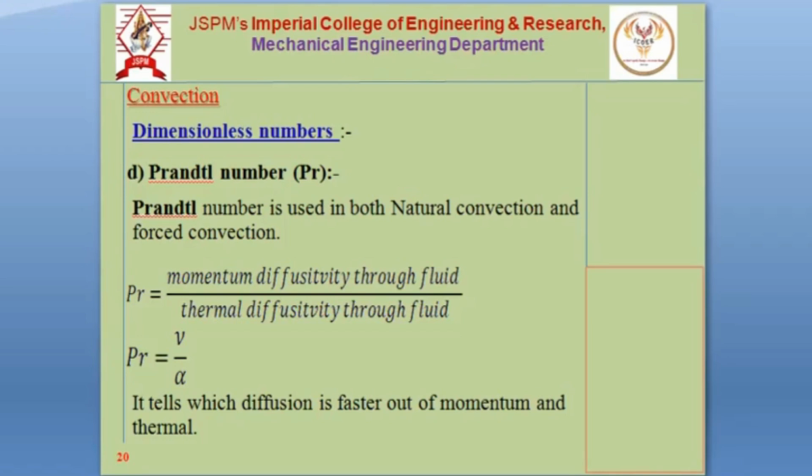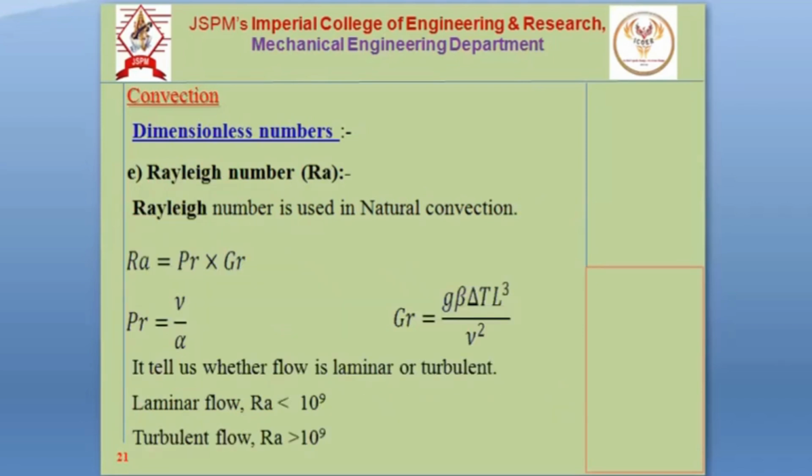Okay. So we know that Prandtl number for air is about 0.7. What is the meaning of that? Which is dominating, thermal diffusion or momentum diffusion? For air, Prandtl number is 0.7. So which is bigger? Thermal diffusion is bigger than momentum diffusion. Which diffuses faster, velocity or temperature? So temperature diffuses faster for air. But it is mostly nearly 1.